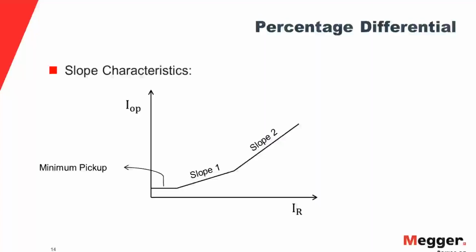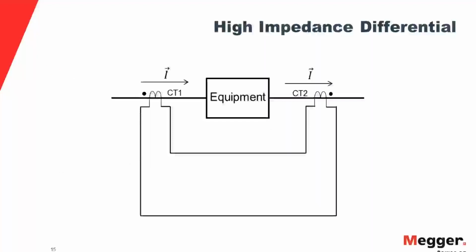When the currents flowing through the system are high because of a fault, the probability of CT saturating is high, because in the power system, most of the CTs are typically operated pretty close to the knee point, and when the excitation current changes because of the fault, then you are pushing the CT into the saturation region. So you don't want the differential relay to operate for a higher fault. So that's one of the reasons why you have a higher slope, especially slope 2.